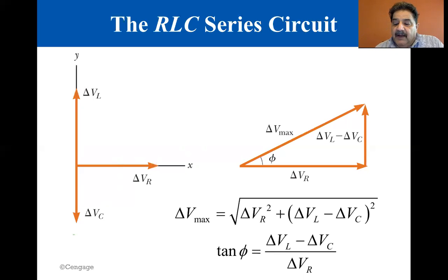This figure reminds you that the voltages across the resistor, capacitor, and inductor are not in phase. So you can't simply add them to get the voltage across the combination of elements or to get the source voltage.